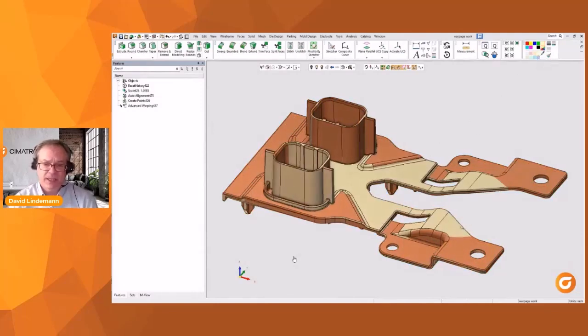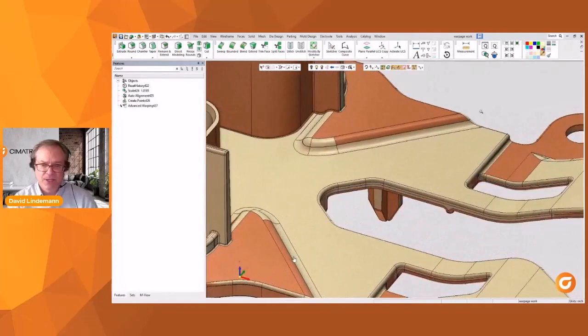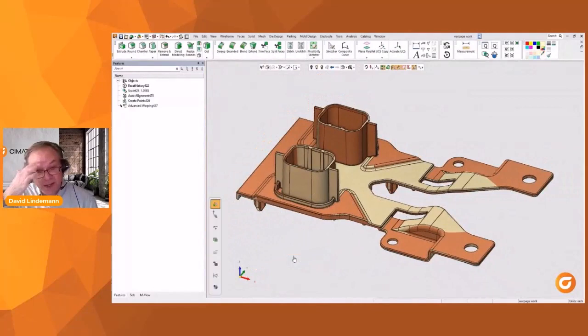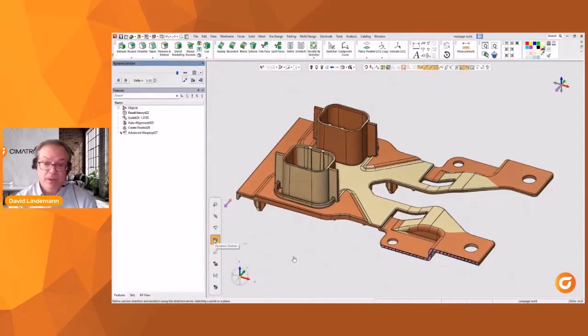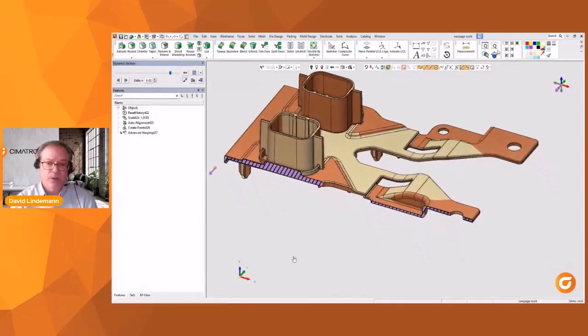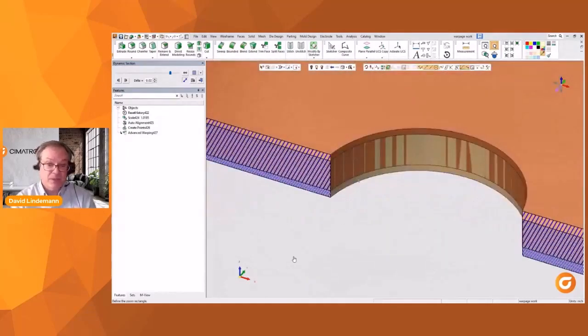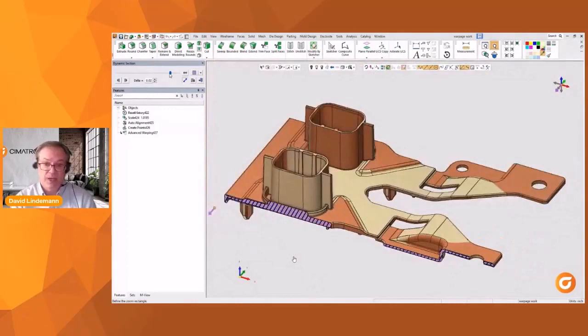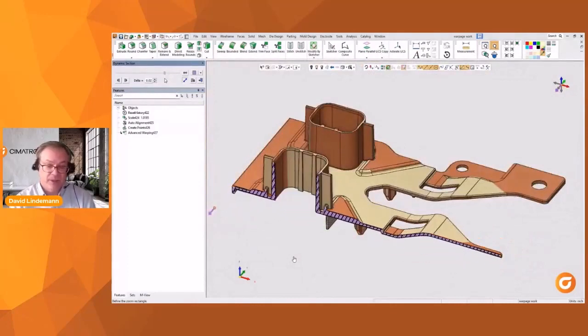So I'm going to take the original CAD file and turn it this yellowy color here, so I can see that versus the file that's got the compensation in it. Maybe there are areas in the geometry I need to adjust. One of the things I need to look at is hole location. I want my holes to still be in the pull direction. So am I still on location where maybe existing core pins already are? Here I could see with the colors bleeding through between the two that yes, it's held those hole locations, so the warpage hasn't affected it that drastically.